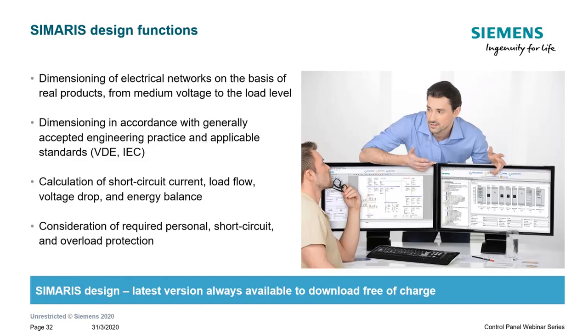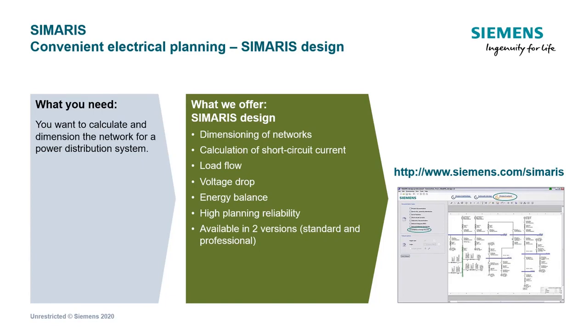Simaris Design is a tool where you can dimension electrical networks on the basis of real products for medium and low voltage. We will focus basically on the low voltage, just to be clear. The dimensioning in this tool is generally accepted by engineering practice. It's based on IEC standards. It calculates short circuit current, the load flow, the voltage drop, and the energy balance, and this is why we're going to use it today.